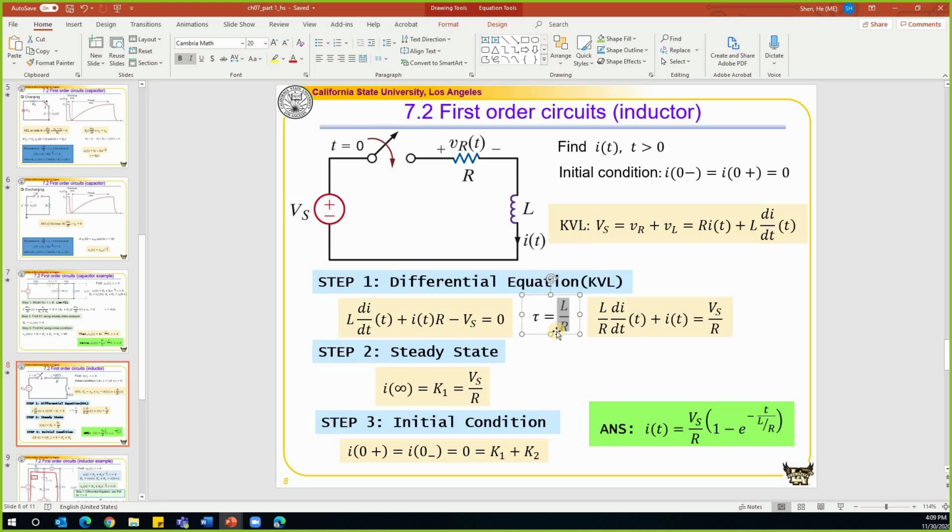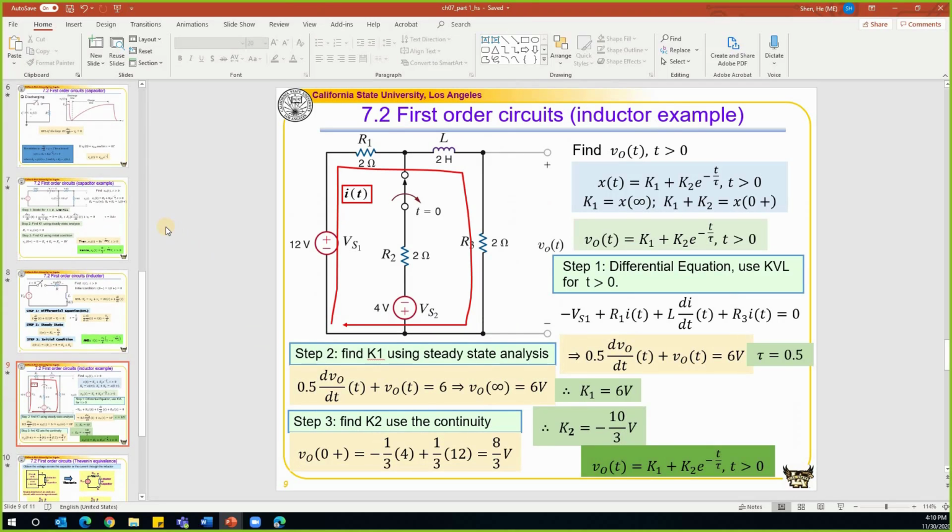greater than 0, right? And we also know from what we learned in chapter 5, the Thevenin equivalent circuit, that for any circuit we can find its Thevenin equivalent circuit. If we take this capacitor or inductor out, and we put the rest of the circuit as its Thevenin equivalent, in that circuit there is only one resistor. We know that this R has to be equal to the resistance of that resistor, right? So if we combine the knowledge we learned from previous chapters, we have a conclusion. This R is equal to the resistance of its Thevenin equivalent circuit. So that is the conclusion that we got.